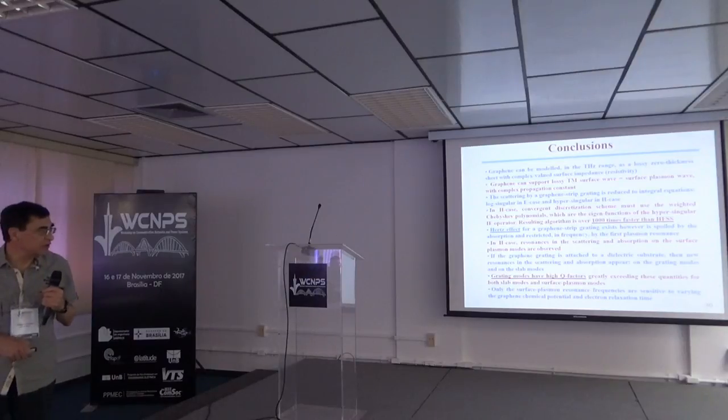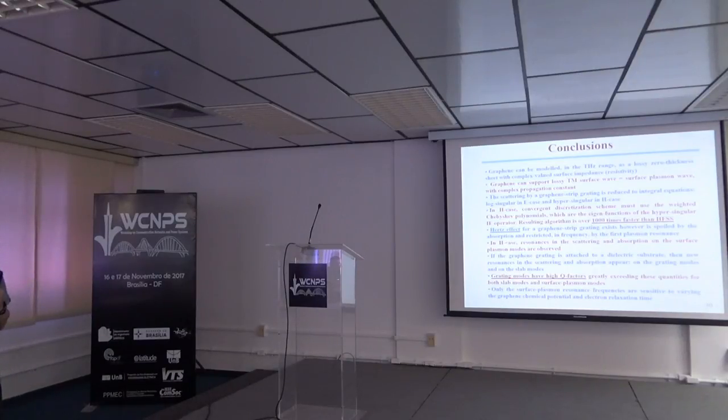There are many interesting physical effects related to graphene, including the classical Hertz effect, but now shifted to lower frequencies, even lower than with metal gratings. And still, the most interesting effect is related to the appearance of the super high quality resonances in the case of a grating deposited on a substrate. This opens the way for thinking about new elements of the terahertz range, new components and new circuits, and finally new applications and new systems. Thank you very much.